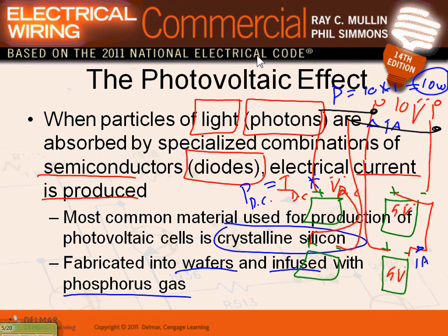You see what we did? We have another 5 volt, another 5 volt. So another 10 volt system. Can I put 2 10 volt systems together in parallel? Yep, they have to be the same. By doing it this way, do you know what the outcome is? You double the current. Now you multiply this by 2. How much current do you get? The current here would be 2 amps now. 2 times 10 is what? 20 watts. You got yourself 20 watts.